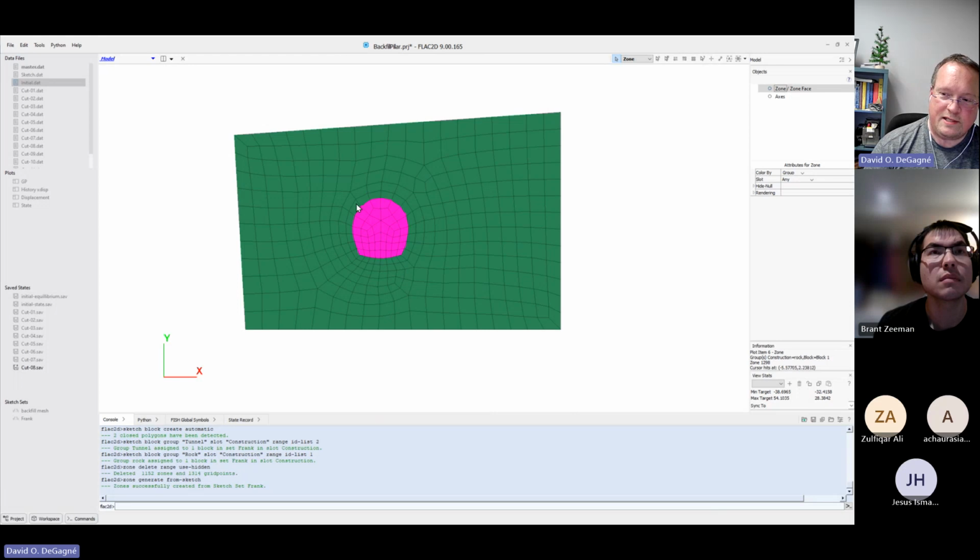And then it would try to do the same thing to the internal boundaries. So it might be like west 1, west 2, just depends on the angle that's involved. But a lot of that can be quite automated, where you can specify it manually. And then when you actually want to assign your boundary conditions, you have a name rather than having to worry about what this coordinate is and that sort of thing.